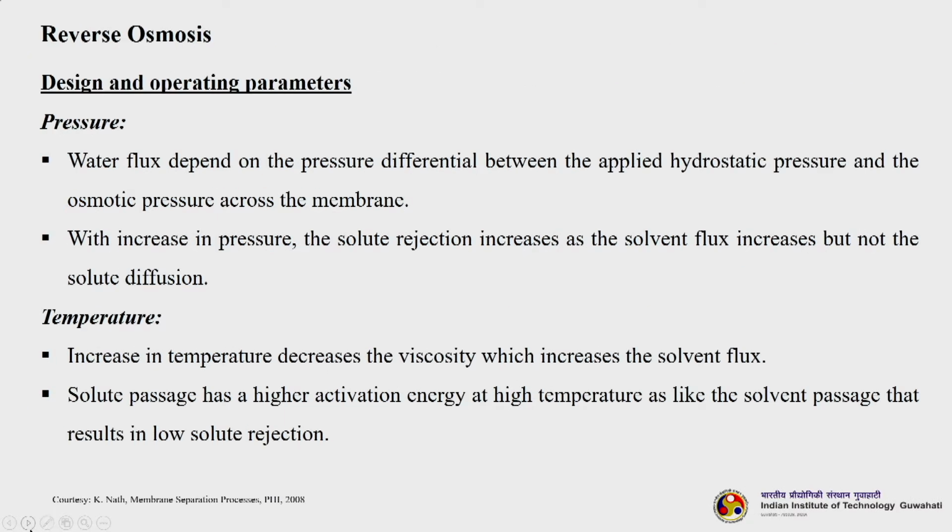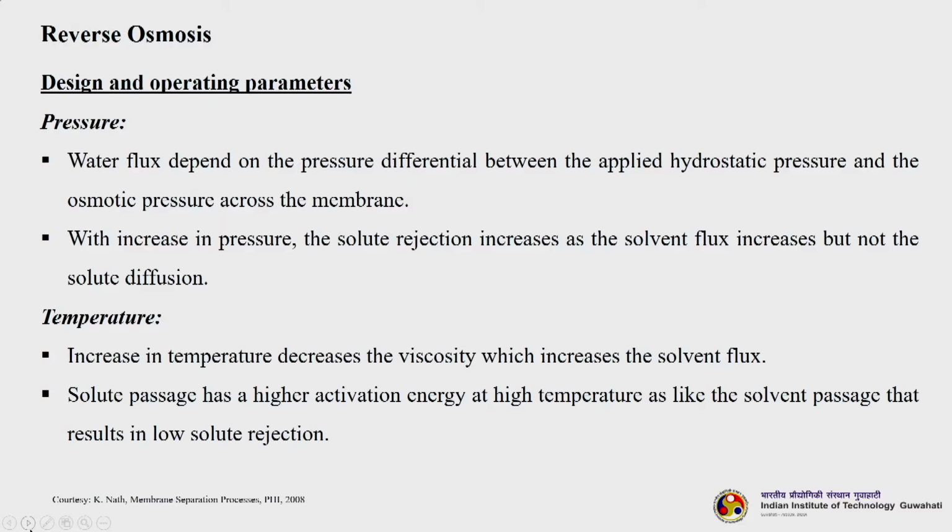Now, let us understand the different design and operating parameters that affect the overall performance of reverse osmosis systems. The first one is pressure. Pressure is the most important parameter. We know that water flux depends upon the pressure differential between the applied hydrostatic pressure and the osmotic pressure across the membrane. With increase in pressure, the solute rejection increases as the solvent flux increases, but not the solute diffusion.